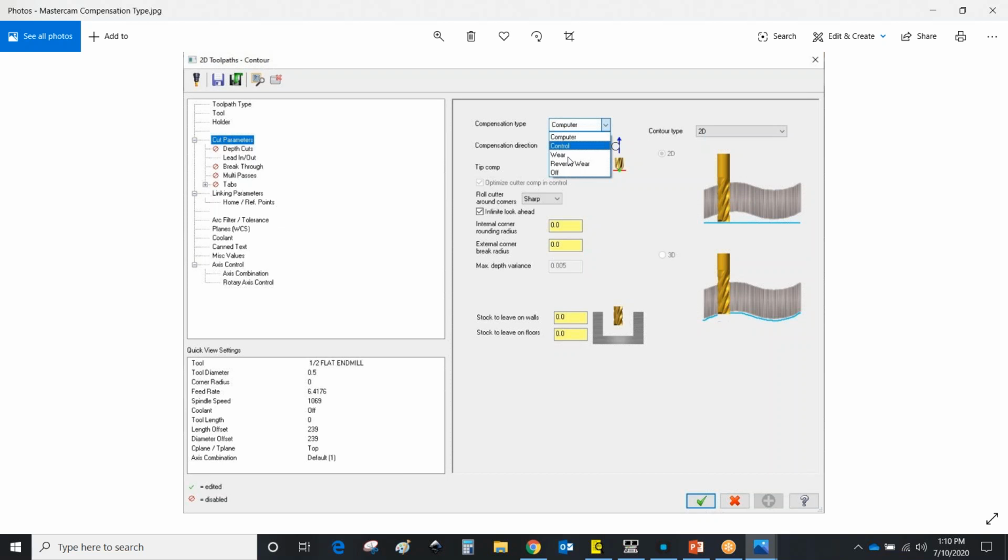It will program as if we were using a half-inch tool, so the geometry in the program will be already offset, but it will give us the ability to add in the D register on this G41 line plus or minus a couple thou to adjust for wear. So those are the three settings that are most common, and probably the most common is the one that I've got highlighted there, the control, which is what I use today. And that is, it expects you to put in the full radius or diameter, depending on the control that you're on. But on Hurco, it's a radius of the tool.